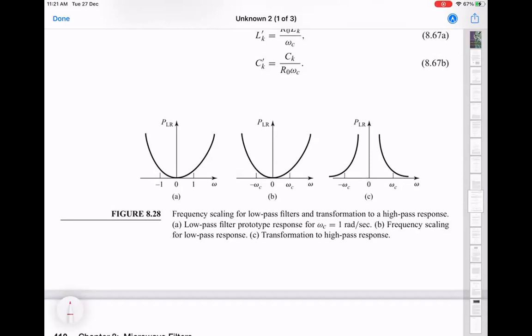So 1 to 2 is a factor of 2. So when you scale the whole thing to 10 gigahertz, that will be the fall you will get as you go from 10 to 20 gigahertz. So it's all ratiometric. You have to keep that in mind when you construct your things, which basically means that if you go to higher frequencies, you need to have higher order filters to get a very sharp response in your filter function.